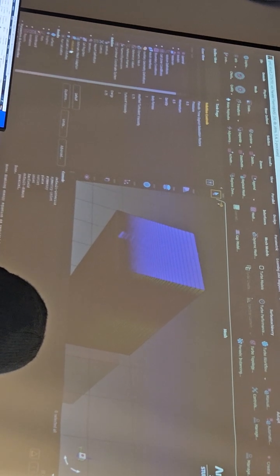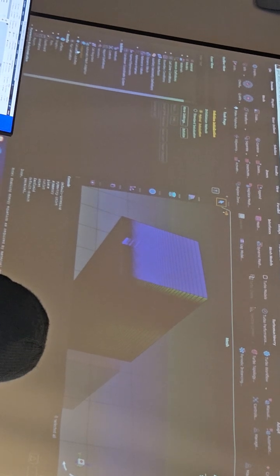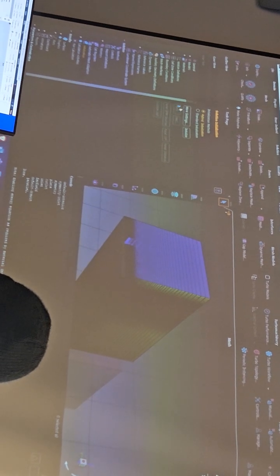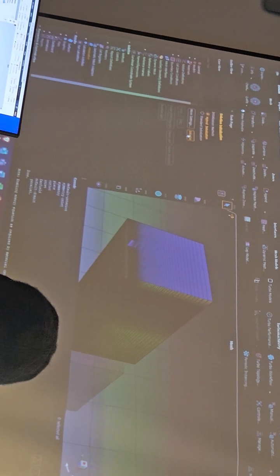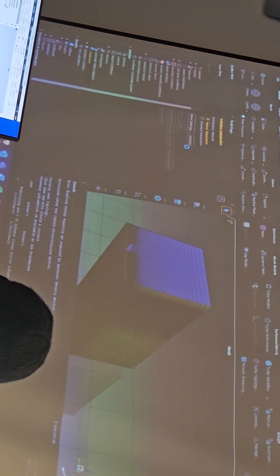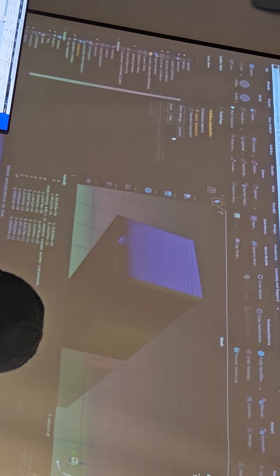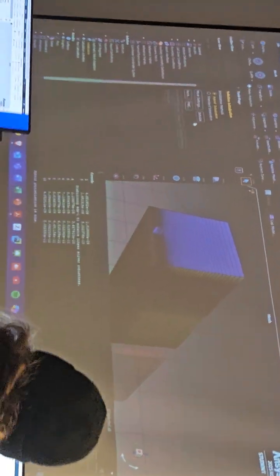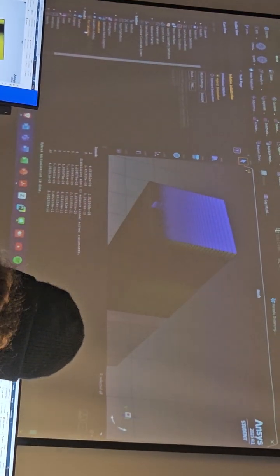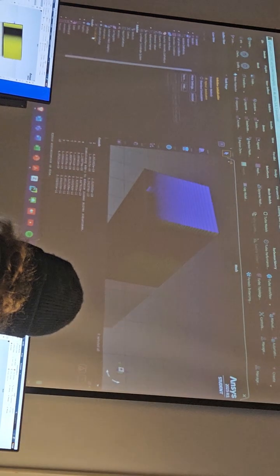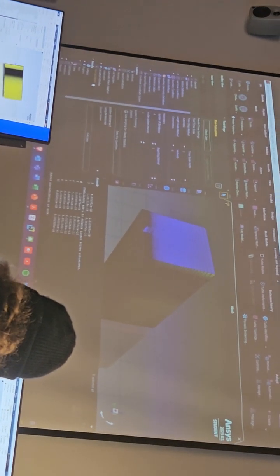So we set everything we needed to. So now we can initialize the problem. So we go in the initialization, and we choose the hybrid initialization, so we can initialize. So we let Fluent do the initialization part. So when it's done, we have already one, let's say, initial solution. At least each cell has a value for every flow variable.